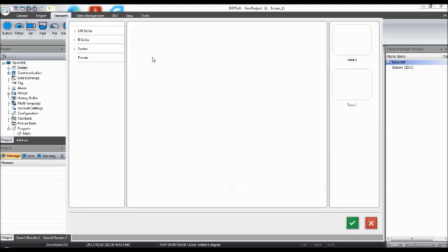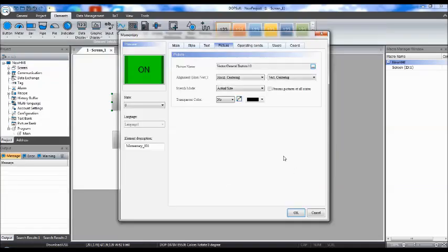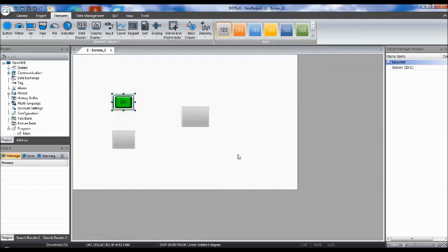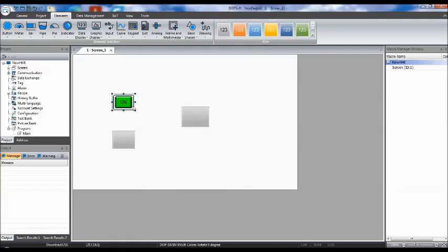you go to the vector, and general buttons are there. So this is the 0 condition, and this is the operated condition, I can take this. Okay, and then there is stretch all, please select stretch all and get this one. Okay, so the on button I have linked to x0, and double click on the other momentary button,